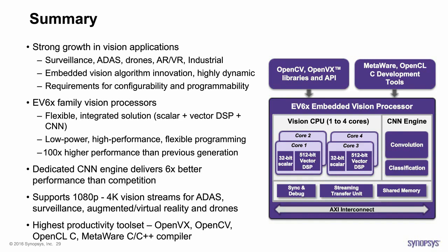It's not really an OS, but that's the system that we run on the processor itself. We don't run a specific OS on the Vision CPU or the Vector DSP. There's no reason why you couldn't, but typically you wouldn't. It just doesn't make sense because it's a very specialized task. So the OS, if you will, is the OpenVX runtime.